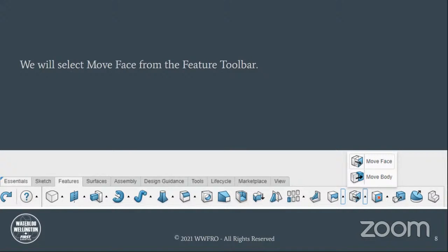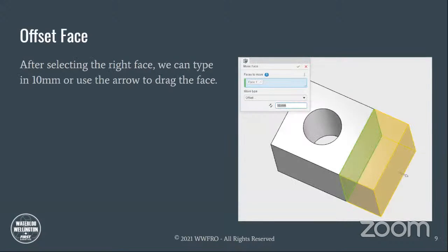So once we have the part in and converted to direct edit, you can see there's a little move face, which looks exactly like that. We've got a rectangle, the face highlighted blue. So we click on that, and from there, we're able to select the face. So in this example, you can see I selected the face on the right. We get the little white arrow that we can push and pull to stretch that part or that face in and out of the existing part.